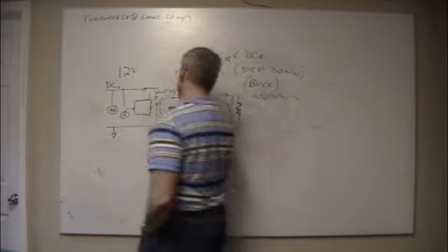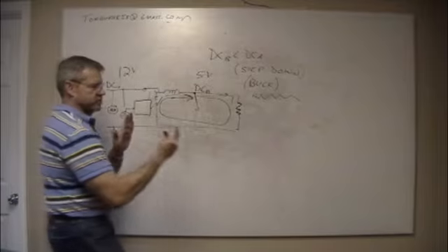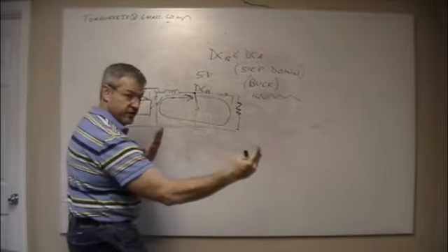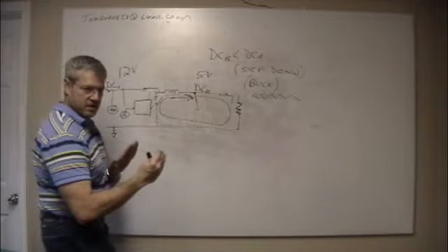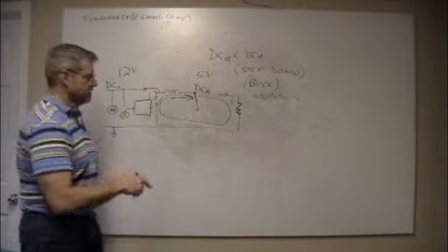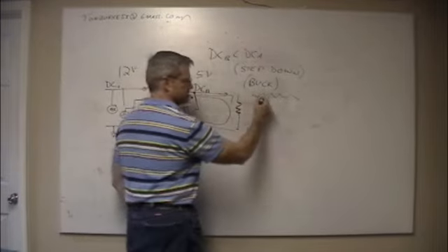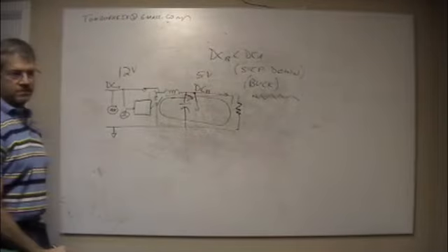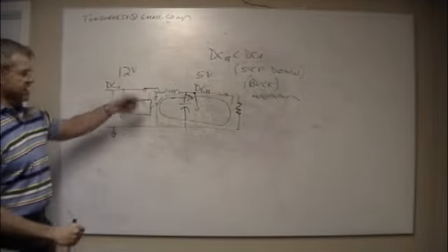But usually what they'll do is it's smarter than that. It pulses, pulses, pulses, and it'll keep pulsing, but it'll change the pulse widths and do a PWM on this to keep it in sync. That's a buck. And now, you throw a capacitor in here too, and now you start smoothing that out. That's how a buck converter works. I'm playing a game with a switch and an inductor.